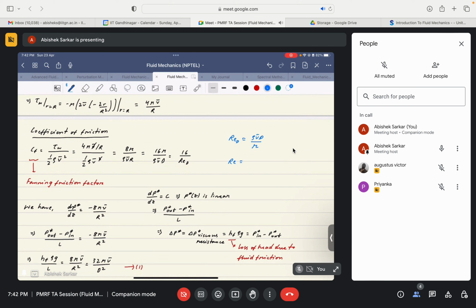So the D here in this case would be replaced by the length of the plate, right? And more accurately, at every location the Reynolds number would vary. So it will basically mean it will be rho V average x by mu, right? I may have discussed this, I may not have, but a Reynolds number should basically be rho V bar L_c by mu, where L_c is the characteristic length scale of the flow field.